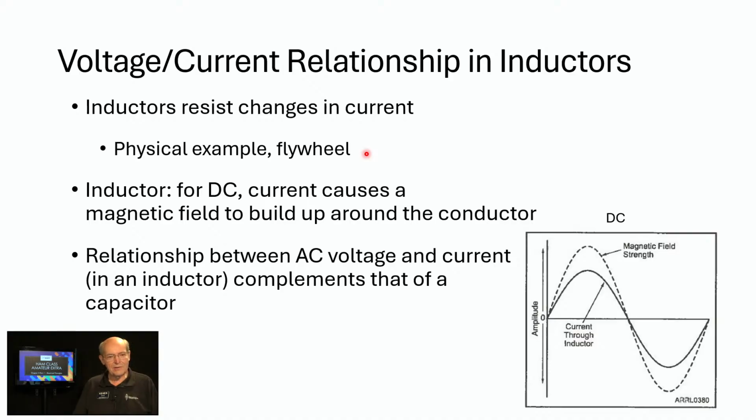Now you might be wondering, why don't I feel these individual pulses? Part of it's because they're happening kind of fast, but the other part is that there's a big hunk of steel inside your engine called a flywheel that smooths that out. So we're giving little impulses to the flywheel, accelerating it every time a cylinder fires, and then the flywheel tends to keep turning until the next one fires, and it smooths it all out. And an inductor works much the same way.